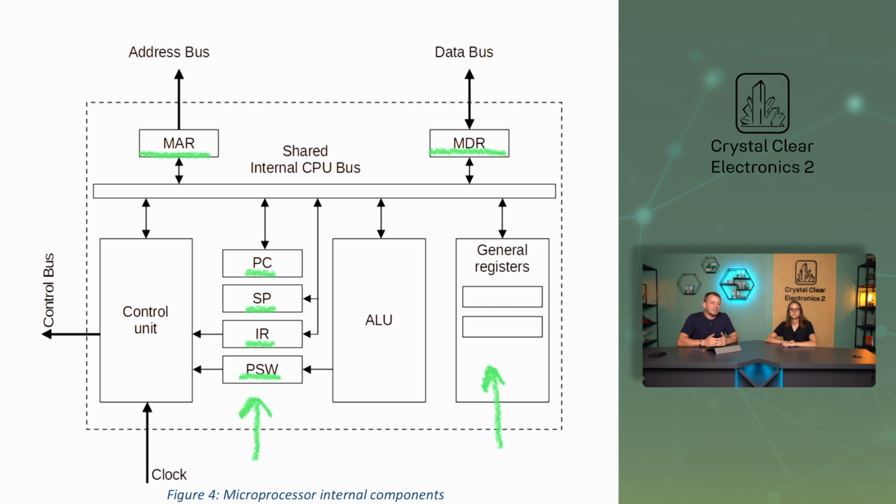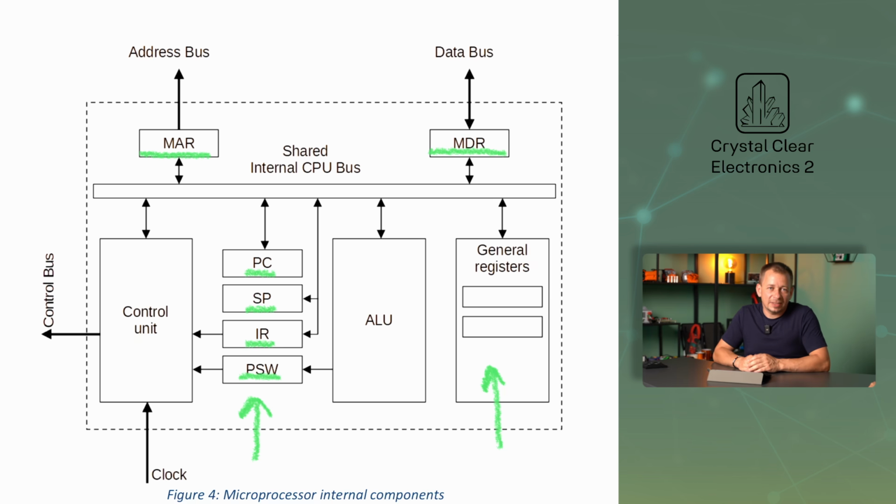Instructions, including addition, use the general-purpose registers in a way that is specific to the instruction. For example, for a given architecture, the processor can go through the following steps. First, it copies the value of the variable a from memory to the general-purpose register R1, then variable b is copied to R2.